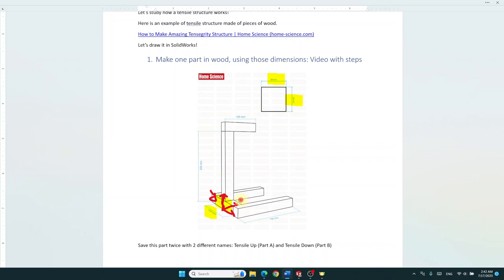So to have a positive referential, that will be x, y, and z. In Solidworks, the x and z are on the bottom plane, so that will be easier to follow the same thing. And that is the y. So what I will do, I will say the plane x and y, draw a section of 28 by 28 and extrude it 135 on both sides.